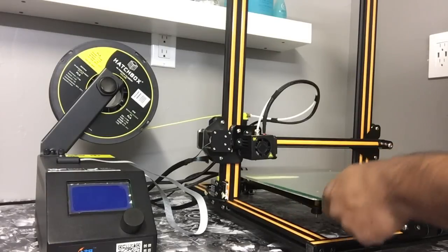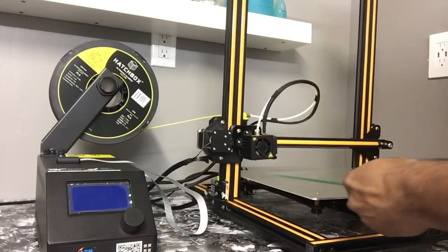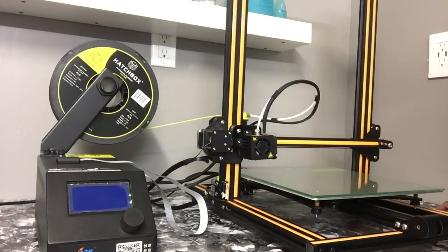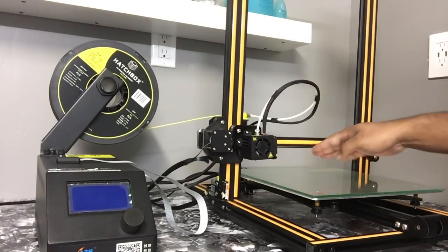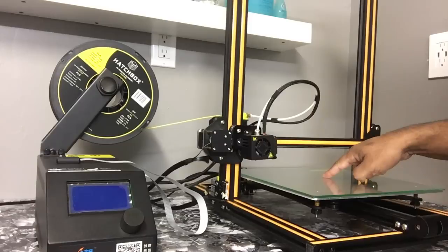Well, that's pretty easy. Take your glass, flip it over, and re-level your bed. Now 50 to 70% I would say that will fix the problem. The imperfection might have only been on one side, but if you're unlucky, you'll probably have the other side bulging up, so not all four corners come out perfect, but this part the nozzle won't even touch because it's so tight, so it'll stop like right here instead of going to the middle.